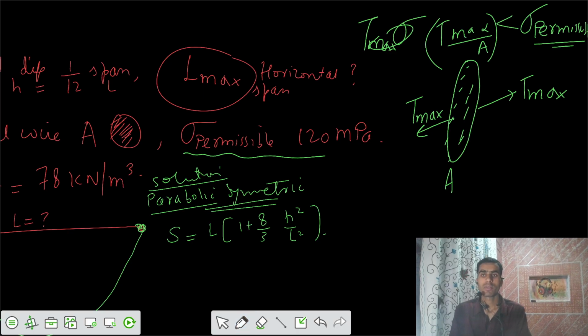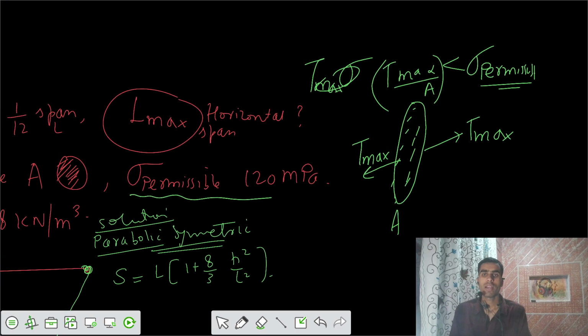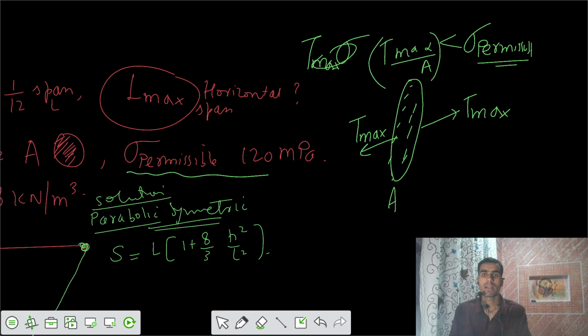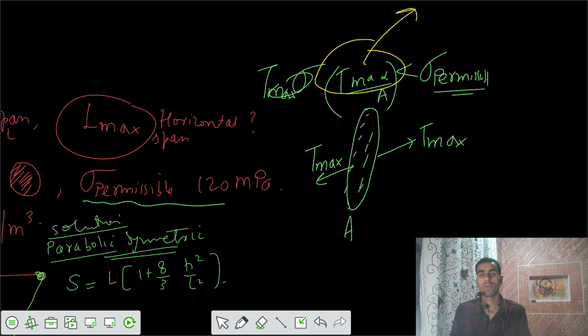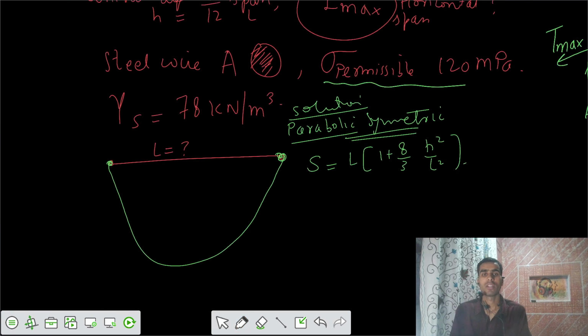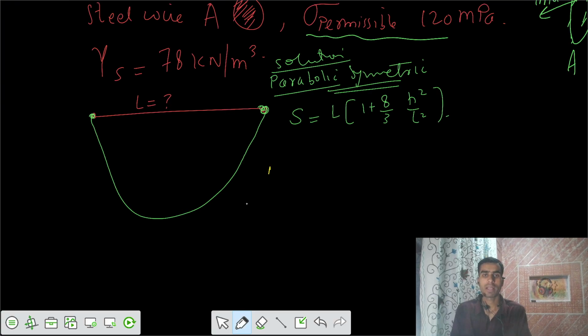Now our permissible stress is provided. We need to get the equation of T max. If our section is safe for the maximum tension, it is safe for all values of stress, because the other stresses would be lesser than that. And we know the equation for T max: T max equals H times 1 plus 16 times...